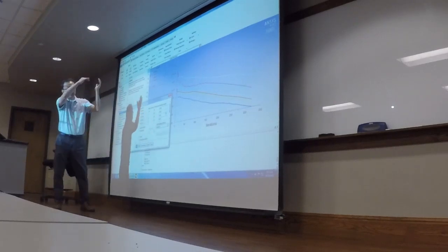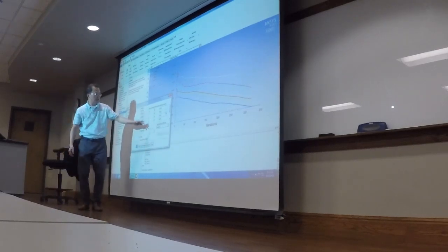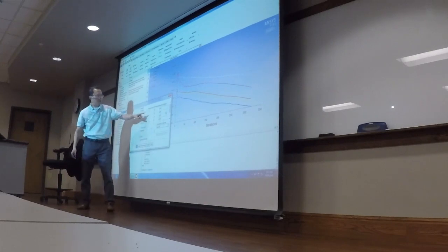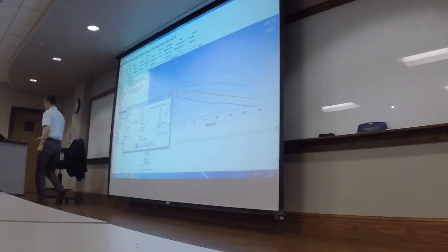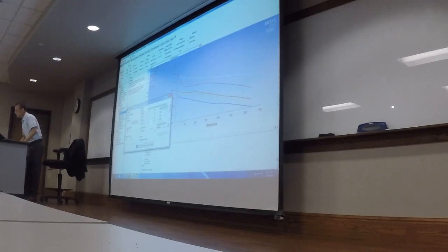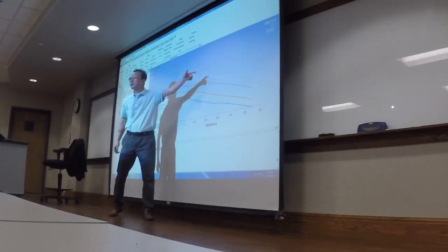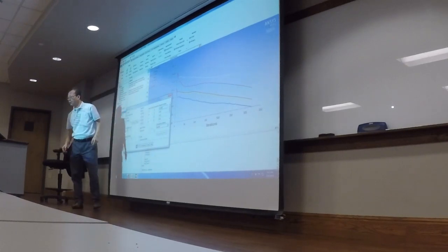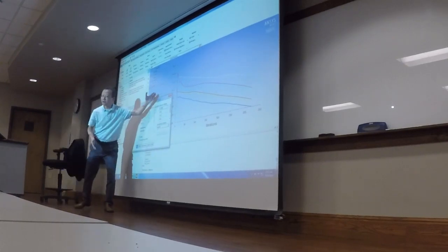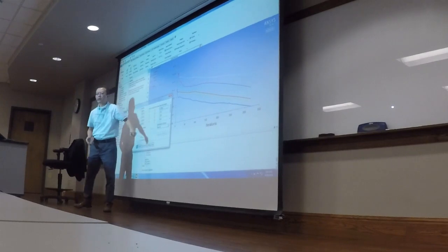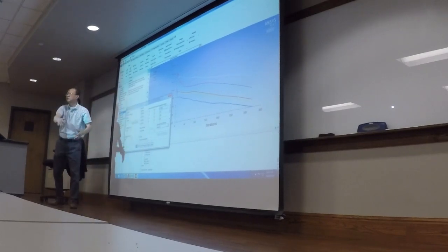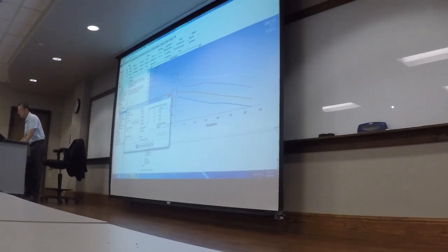You see, all these lines are going down, still going down. So what I would like to do is, for this continuity equation, let's put 2 more zeros. Instead of 0.001, let's give it 2 more. Right? And usually, this continuity equation, which solves for the pressure, it is always the hardest one to converge. So you don't need to change everything, just the first one. Right? So I want this to continue. Okay. Then go to run calculations.